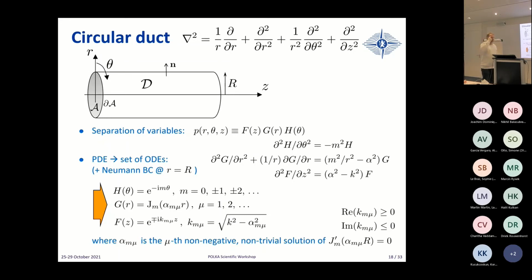So another thing that becomes really puzzling is when you have a mode that is decaying and then you re-enlarge the duct and then it becomes propagative. Because an evanescent mode, in theory, by the equations, doesn't carry any acoustic energy. If you calculate the acoustic intensity associated with the cutoff mode, the energy is 0. But still, if you re-increase your duct, then it becomes passing again. And then there is a conversion between non-propagating to propagating modes of a mode that was not containing energy initially. So then the discussion starts to be a little bit more tricky.